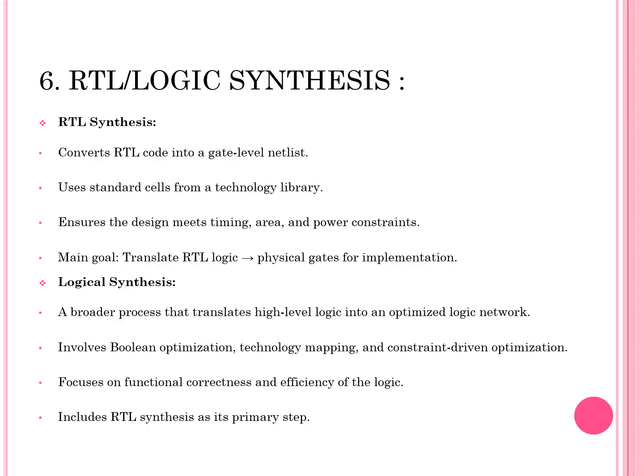In simple terms, it translates high level behavioral code into real hardware logic, the physical gates that will later be implemented on the chip. Now, moving to logical synthesis, it's a broader concept that covers the entire logic optimization process. It includes steps like Boolean optimization, technology mapping, and constraints driven optimization. The main aim is to ensure the design is functionally correct, efficient, and optimized for implementation. Overall, RTL synthesis is a subset of logical synthesis focusing on converting the RTL design into gate level hardware.